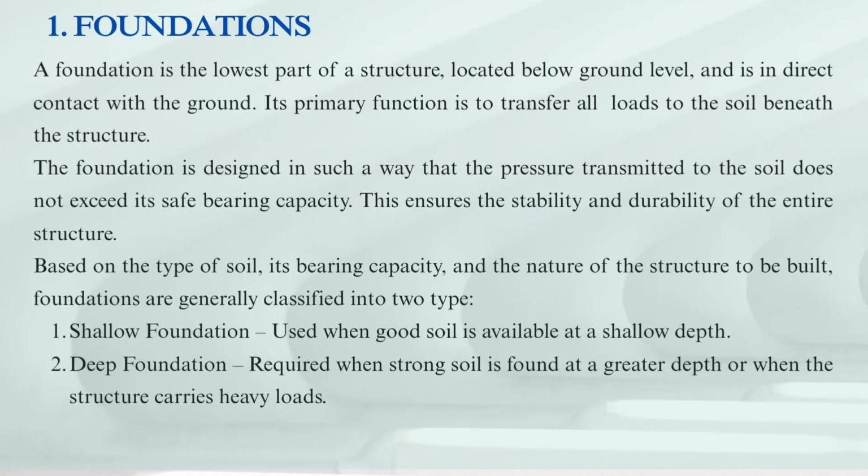So let's start with the very first and the most important part of a structure, that is foundation. A foundation is the lowest part of a structure located below the ground level and it is in direct contact with the ground. Its primary function is to transfer all the loads to the soil beneath the structure. The foundation is designed in such a way that the pressure transmitted to the soil does not exceed its safe bearing capacity. This ensures the stability and the durability of the entire structure.